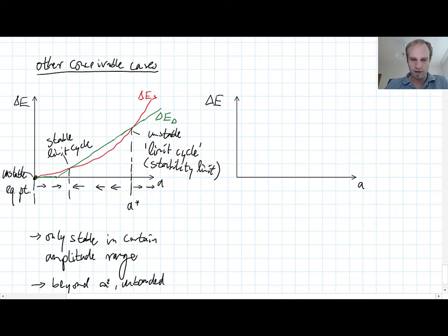Up to a certain amplitude, we have only sticking, so no energy is dissipated, and in this range, once we are sliding, the energy will increase with the amplitude linearly. So the energy that's dissipated in the frictional hysteresis cycle increases linearly with amplitude, and that's precisely the situation shown here. So if we have self-excitation, for instance, due to an aeroelastic instability, plus we have some damping that's dominated by dry friction, then this is actually the typical behavior.